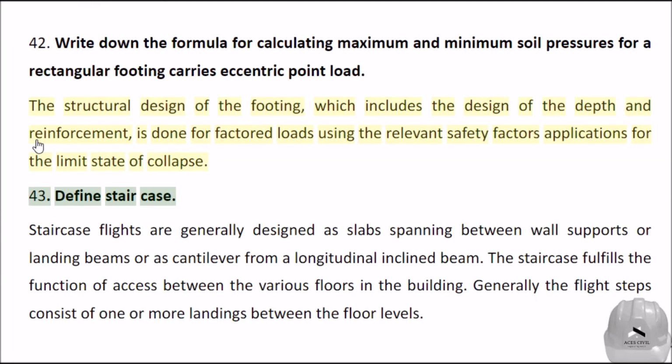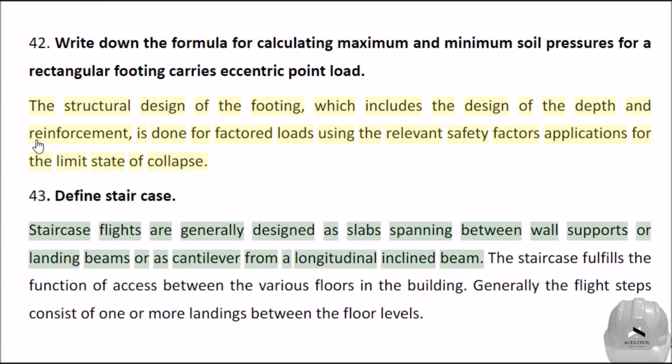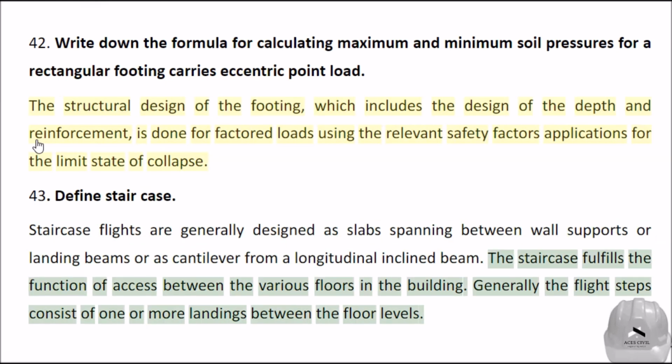Define staircase. Staircase flights are generally designed as slabs spanning between wall supports or landing beams, or as cantilevers from a longitudinal inclined beam. The staircase fulfills the function of access between the various floors in the building. Generally, the flight steps consist of one or more landings between the floor levels.